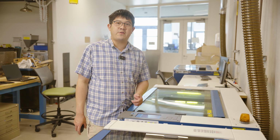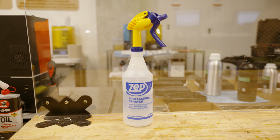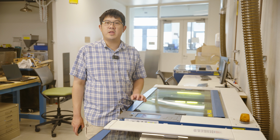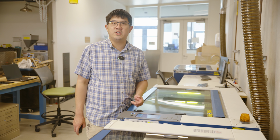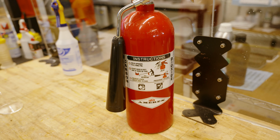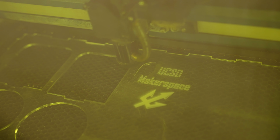In the rare case of the fire spreading or going on top of the material, there are spray bottles located on the desks. Hit the pause button, open the door, this will stop the laser, but the head may keep moving for a second. Spray the fire and come find a staff member to see if we can help you diagnose what went wrong. For serious, much larger fires, we have CO2 fire extinguishers located on the table behind you, and you can tell it's a CO2 fire extinguisher by the large black nozzle.